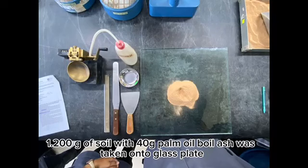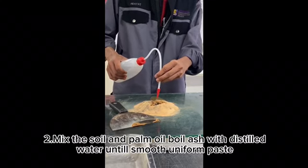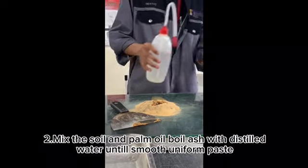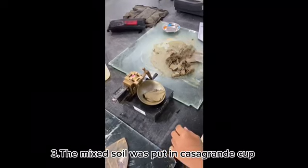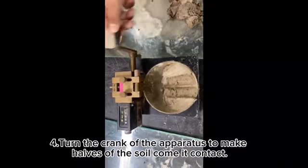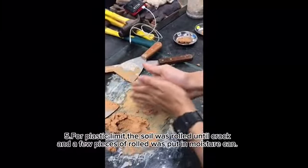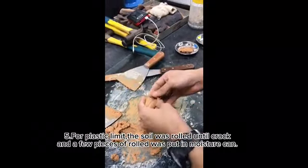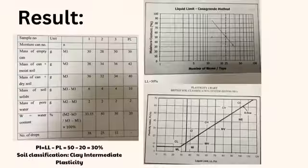200 grams of soil with 40 grams palm oil boiler ash was taken onto the glass plate. Mix the soil and palm oil boiler ash with distilled water until a smooth uniform paste. The mixed soil was put in the Casagrande cup. Turn the crank of the apparatus to make the halves of the soil come in contact. For the plastic limit, the soil was rolled until cracked, and a few pieces of the roll were put in moisture content cans. This is the result from this experiment.